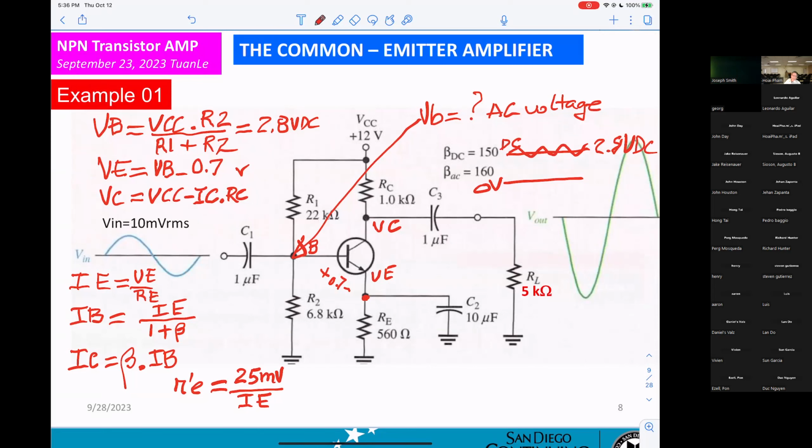When you're using the oscilloscope, the scope used in the class, the first thing you need to do is set it up. First window for channel 1, second window for channel 1, next will be channel 2 and channel 2. That is the first thing you have to set. Then the second thing, you have to set the first window to measure the V peak to peak, and the second window to measure the frequency.